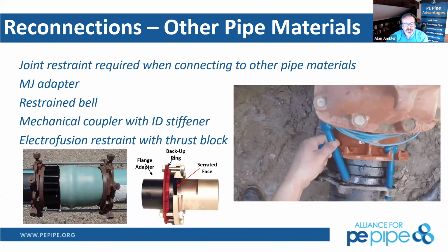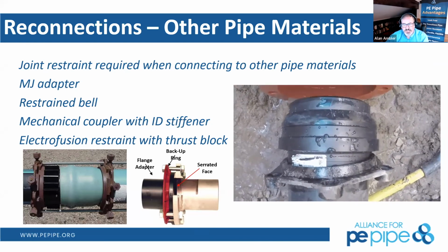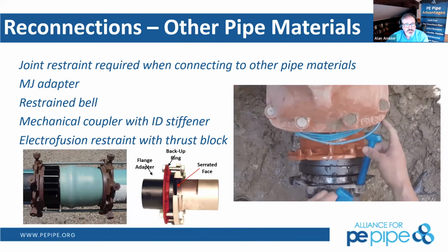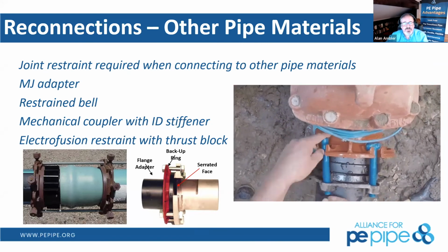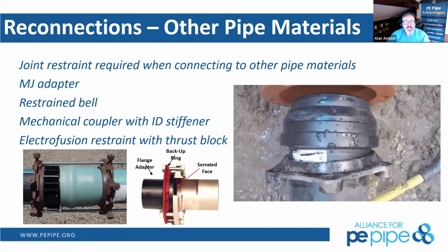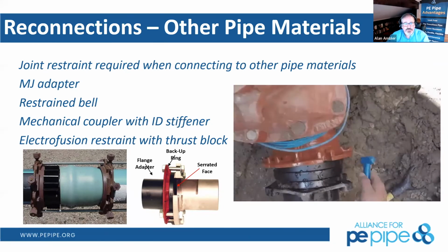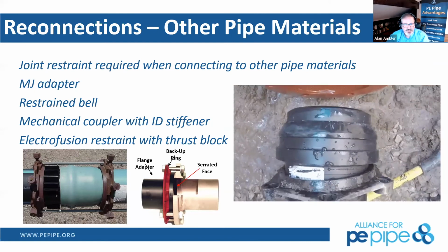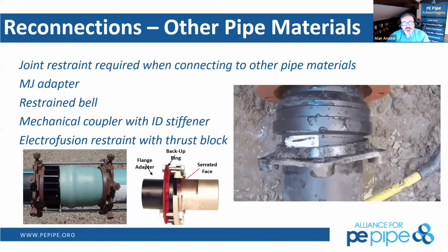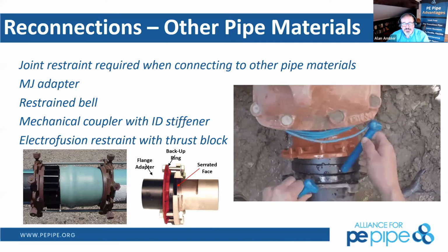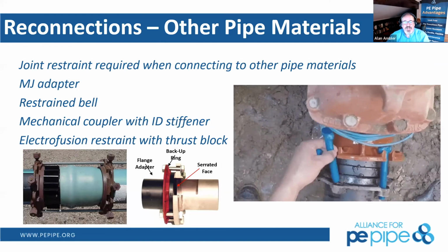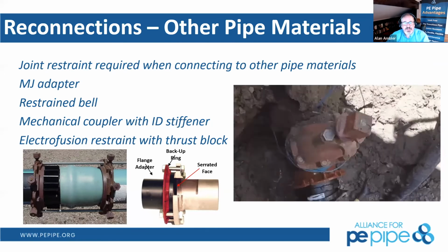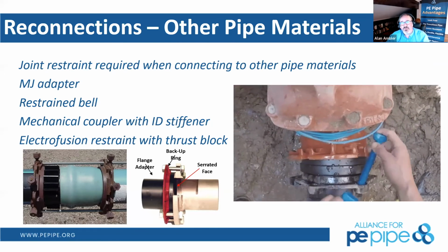So here we've had a great question about municipalities, whether or not they need to have special spare parts when they start to use HDPE pipe. A long-standing response from the industry was, once you install HDPE, it does not fail, so you don't need to make repairs. And a lot of municipalities out there go, oh yeah, we don't buy that for 1 second. But most of the damage to high density polyethylene happens to come from third-party damage, which none of us control. And there are lots of repair clamps and repair fittings available for you.